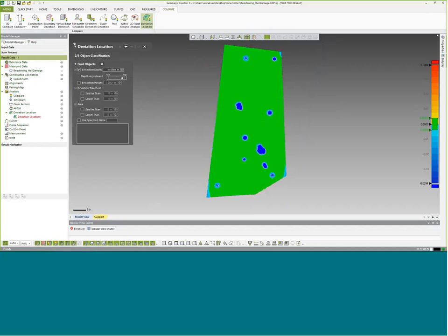So right now we're saying that everything that's basically 20 thou or deeper is being outlined. Maybe we want to increase that a little bit more, to something a little more reasonable. We'll do something like 50 thou, and see if anything's further down than that. That'll be our things of interest. So you see automatically it got rid of a couple things that were very shallow on the surface here. And it highlighted everything else, gave them a nice little tag here just to let us know what it's doing.